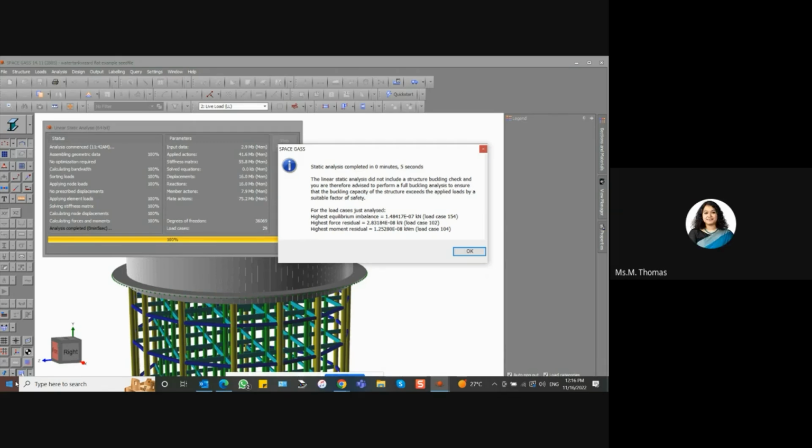The login and password you'll have is for your operating system, not for SpaceGass, because you're not administrator, right? But it is popping up. When I'm opening the SpaceGass software, at that time it is asking login password, and that is what is happening. No, that is the issue. You need to reset your registration using the utility. Run the SpaceGass utility and reset your registration.